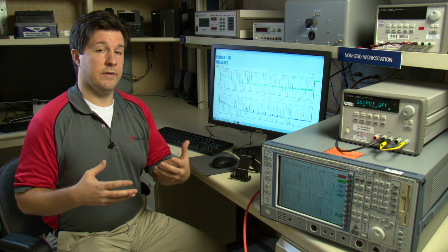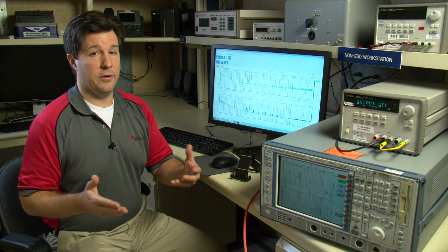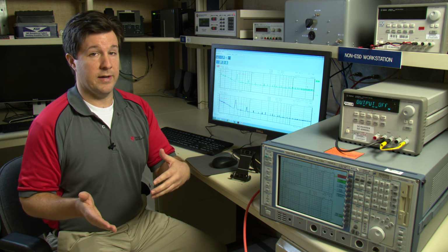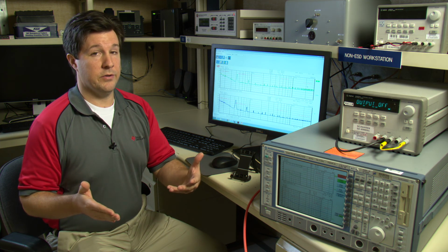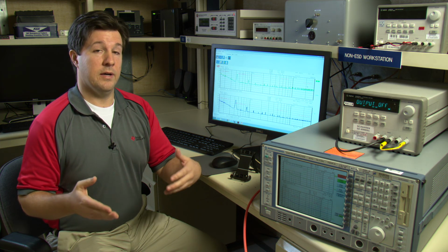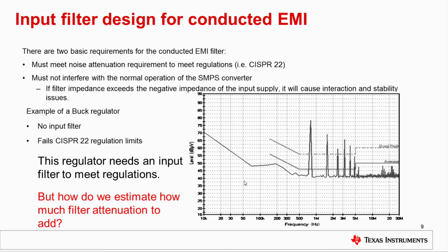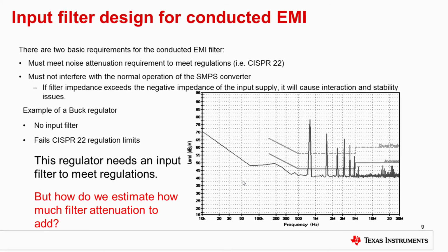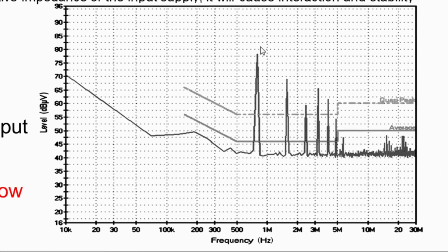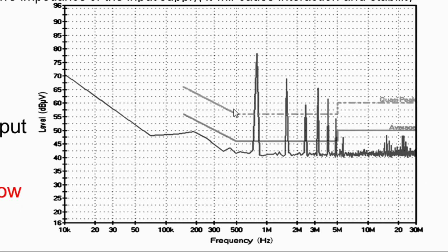Now, in this circumstance, we allowed WebBench to do the input filter design. But if you want to do the input filter design yourself, let me show you how to do that. So you can see on this slide, what we have is basically you're seeing the noise spectrum that we saw for the first EVM with no input filter. So you can see here's your fundamental, and they're well above your average and your peak limits.